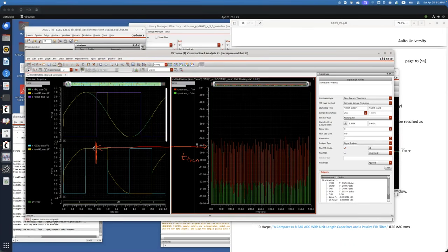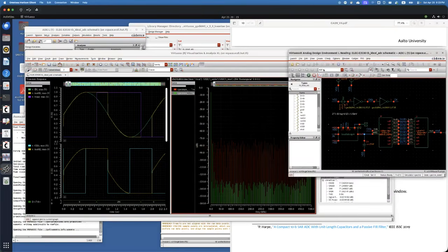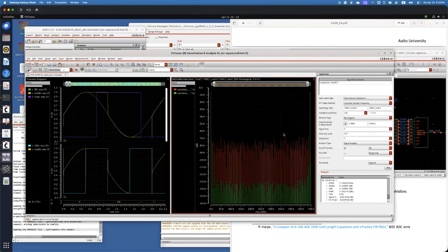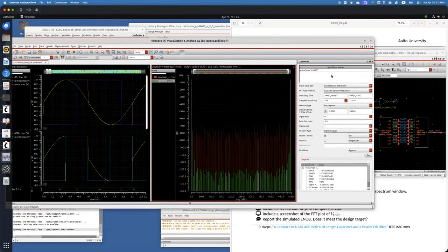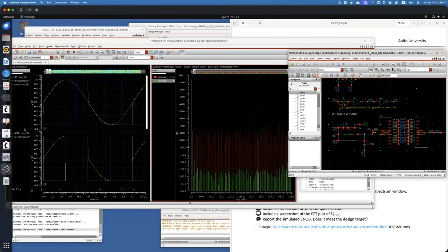Then we can make sure we are getting samples at this point only, not in an indefinite range, for example either here or here. So you can see that obviously its distortion level is far lower than the quantization noise. The green curve is the point at the output of the sampler, and the red curve is ADC plus DAC.